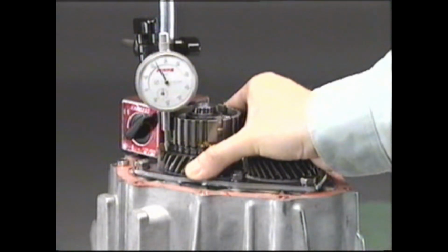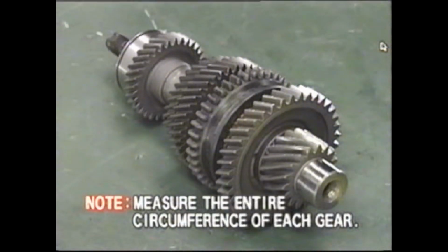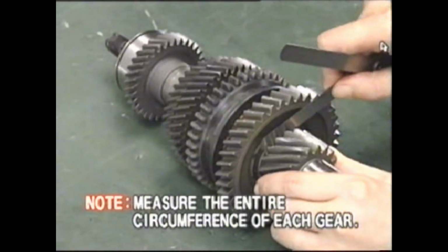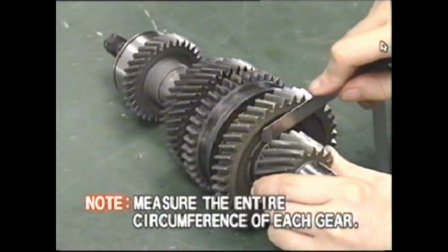Before disassembly, do not forget to measure and record the thrust clearance of each gear. Use a dial indicator for the 5th gear. As for the other gears, use a thickness gauge to measure the thrust clearance. In each measurement, check the thrust clearance around the entire gear circumference.